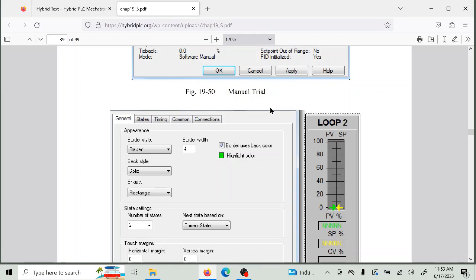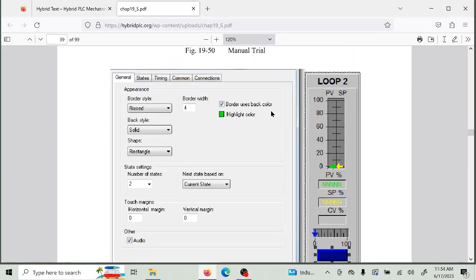You also need good air, and my recommendation there is, instead of having air coming in from an unknown supply, put your own little compressor in and have a compressor local to you that you can eyeball, that you know is dry, because if somebody else moves the air supply around and doesn't put a dryer in, it'll get wet, and that's not good.